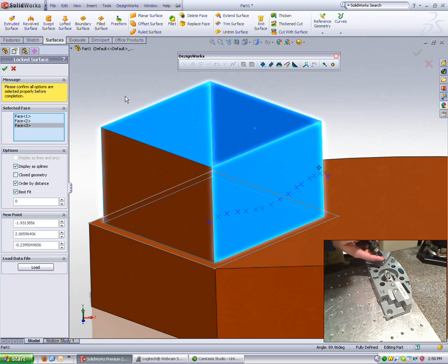The key thing here is that we're able to take the probe and just scrape it across the surface in any direction, in any orientation, and as we move across that surface we're getting a point at every instance. We can also identify how close those points are placed to each other and what the tolerance is across that surface. The nice thing that you'll also see is that we have the ability to get either splines or just reference points. And here we're doing splines, and we're creating individual splines. We could also have closed splines as well.